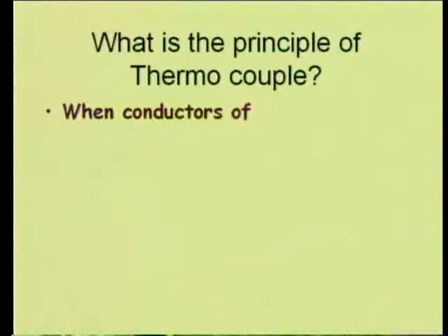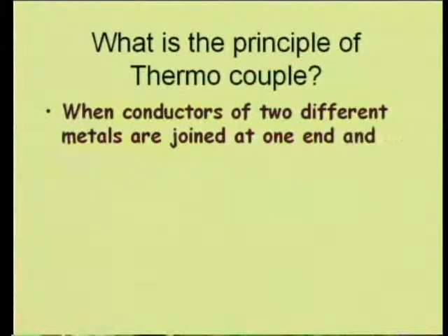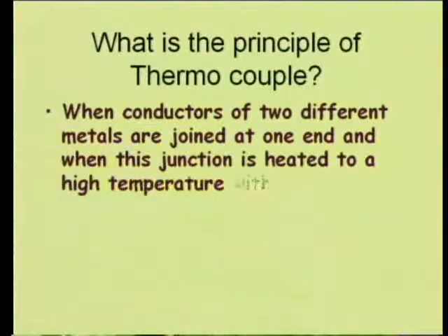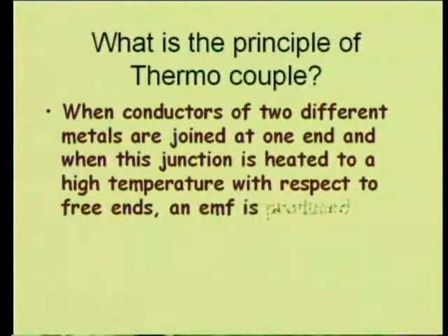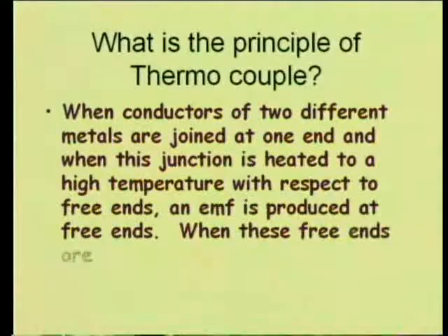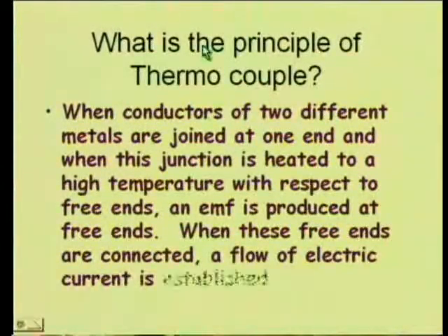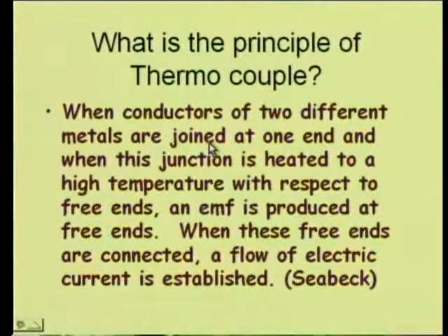Now we go for the principle of thermoelectric pyrometer. Here, another thing that comes is the thermocouple. When conductors of two different metals are joined at one end, and this junction is heated to a high temperature with respect to the free ends, an EMF is produced at the free ends. When these free ends are connected, a flow of electric current is established.